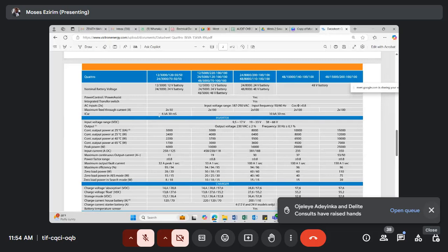Can you see it? Hybrid inverter has input DC, battery inputs, AC inputs, AC outputs, and it is mostly used in DC coupled system. Battery inverter doesn't have DC input. It only has battery inputs, AC input, and AC output. That's why we use external charge controller for battery inverter. Now, an on-grid inverter or solar inverter only has DC input and AC outputs. Do you get that now? Yes, sir.